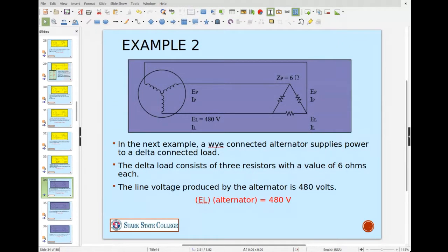All right, another voltage that we see a lot in use is 480 volts. Okay, and this kind of just goes back to the transformers we talked about last week. If you increase your voltage, you can transfer the same amount of power with less current. Less current means that your conductors are smaller and your loss due to the resistance in the wires is smaller because your actual current is smaller, right?